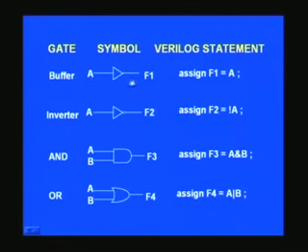So the corresponding Verilog statement is assign, this is the important thing, mandatory in order to assign any statement. This is the output on the left hand side of the equal to, and it's almost like a C program, right, with the exception that assign is a new thing here. It's because this is a hardware field.